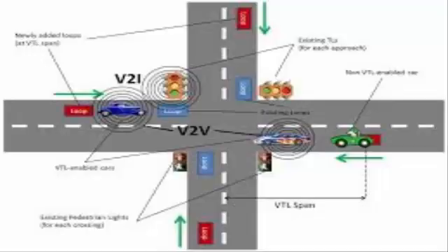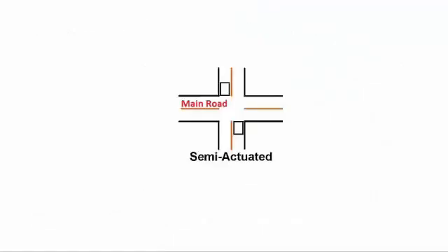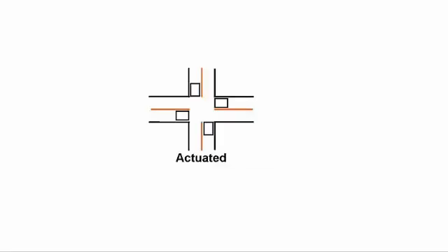The system works by adapting itself to the number of vehicles by measuring the volume of vehicles that are on the road at any moment, and then it sets the interval and frequency for traffic lights to work accordingly. There are two types of controllers that are used for different traffic flow settings. One is semi-actuated and the second is full actuated.